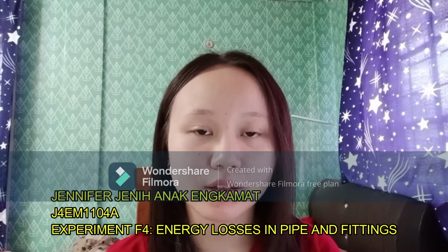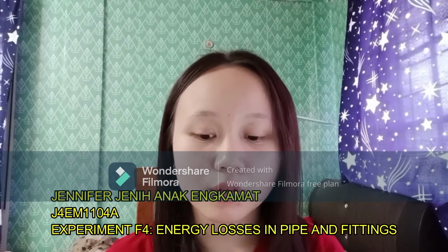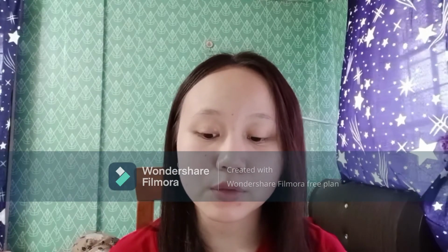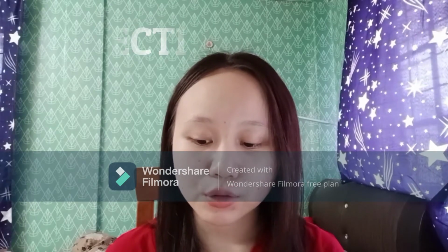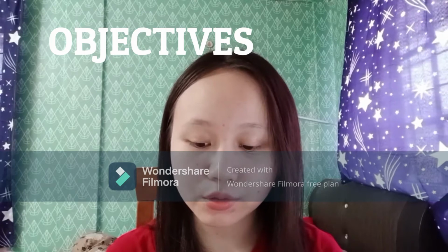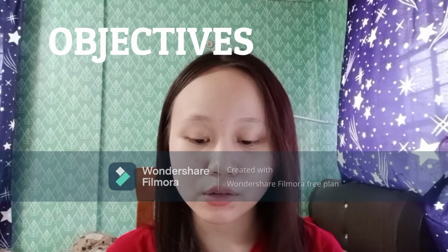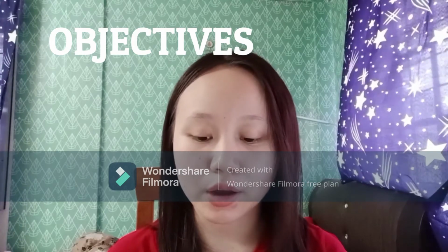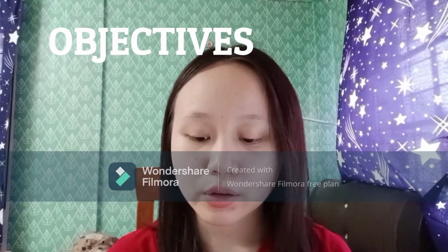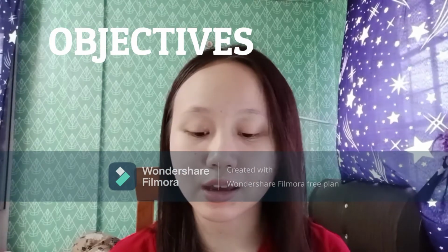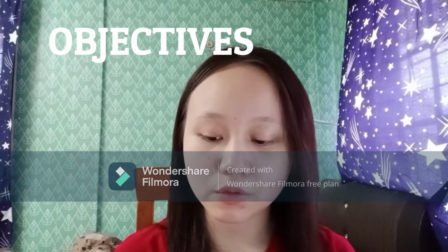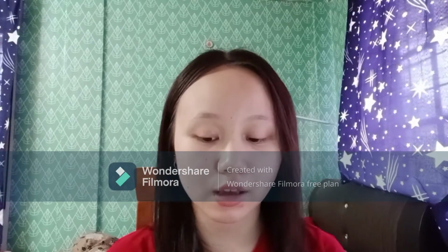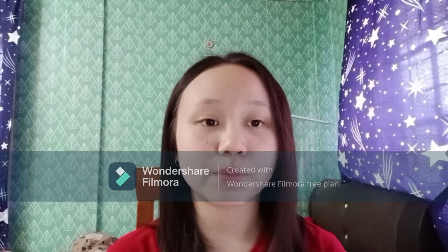So today I'm conducting an experiment, which is experiment F4, energy losses in pipe and fittings. The objectives of this experiment are to determine the losses in the pipe fittings related to flow rate, Q, and to determine the loss coefficients related to velocity head, K. One more objective is to compare the losses of energy, or head losses, H, in different configurations of pipes.